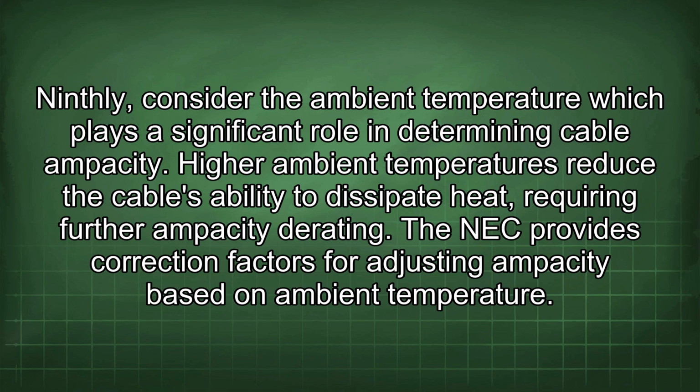ambient temperature, which plays a significant role in determining cable ampacity. Higher ambient temperatures reduce the cable's ability to dissipate heat, requiring further ampacity derating. The NEC provides correction factors for adjusting ampacity based on ambient temperature.